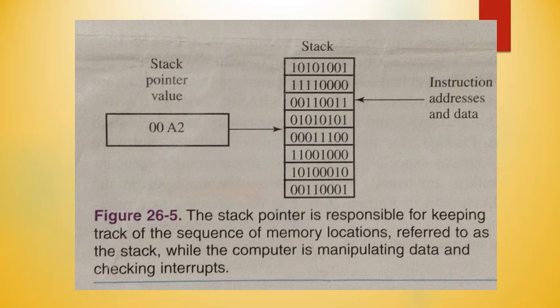The watchdog timer. A specialized program, often found as parts of the microcontroller, is called a watchdog timer. The watchdog timer is designed to prevent a microcontroller from halting or locking up because of a user-written program. Remember that a processor processes instructions step by step. It will wait until one instruction is completed before processing the next. A problem can arise if a command is issued to a processor that cannot be accomplished.